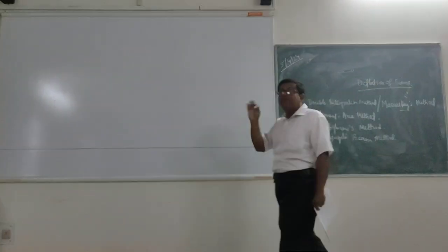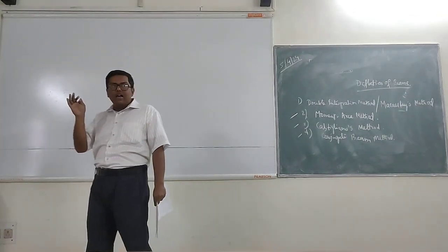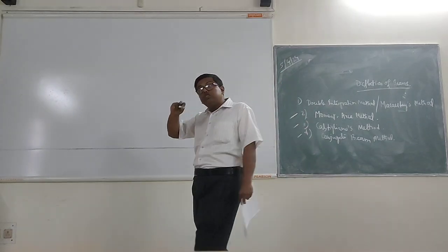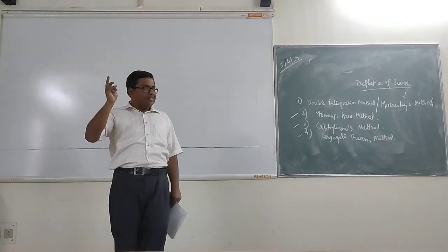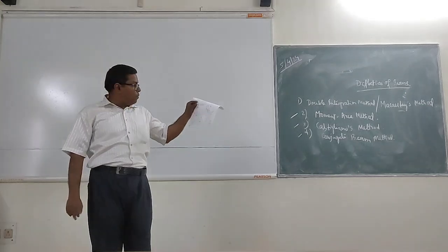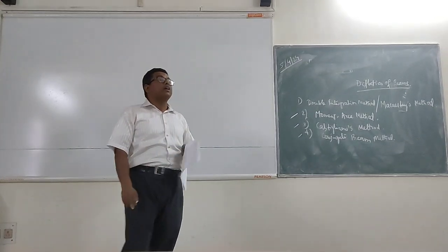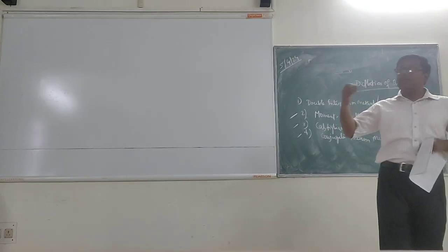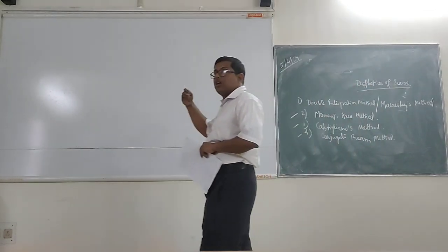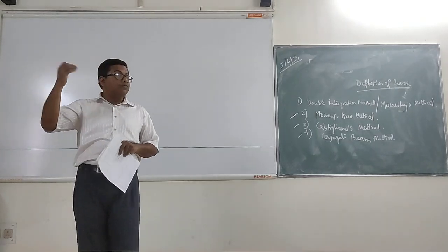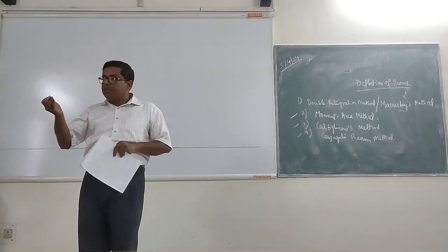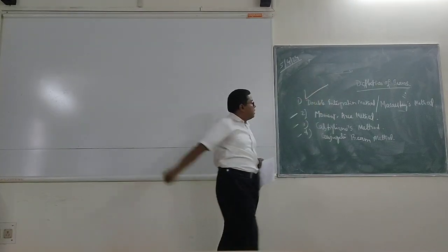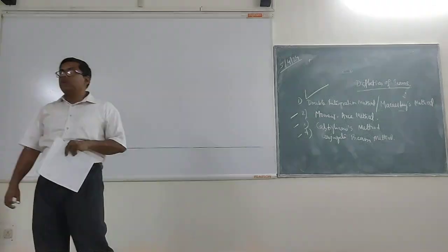So if you can relate the deflection of a structure to something, and find out the deflection, then you can also solve the indeterminate structure. So Castigliano's method, moment area or conjugate beam method are very effectively used for finding the different internal and external forces in indeterminate structures, through finding the deflections in the structure. Clear? But in this semester, we will be learning primarily the double integration method and Macaulay's method.